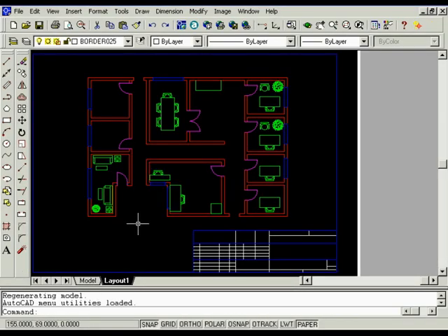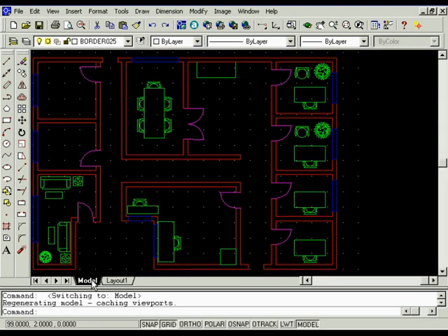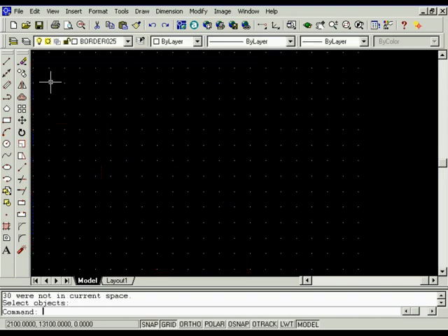Creating a drawing template file. Choose the Model tab at the bottom of the drawing area to indicate that you want to work in model space. On the Modify toolbar, choose Erase. At the command prompt, type All and then press Enter. Press Enter to indicate that you do not want to select any more objects. The objects you selected are erased from the drawing.